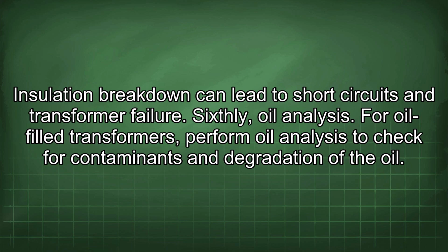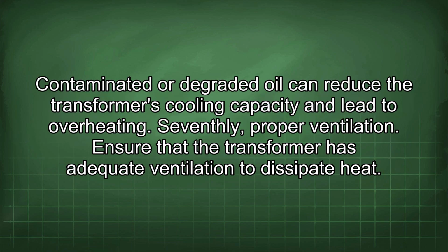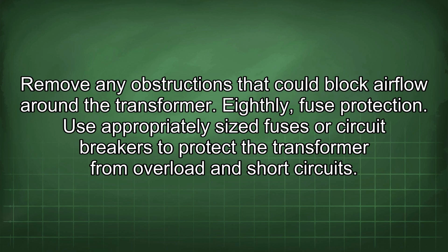Sixthly, oil analysis. For oil-filled transformers, perform oil analysis to check for contaminants and degradation of the oil. Contaminated or degraded oil can reduce the transformer's cooling capacity and lead to overheating. Seventhly, proper ventilation. Ensure that the transformer has adequate ventilation to dissipate heat. Remove any obstructions that could block airflow around the transformer.